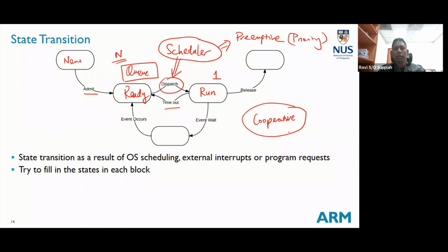It's a round robin kind of thing where you transition between every task, giving an equal share to the different tasks in the system. In an RTOS, you have to have a scheduler that is preemptive in nature and where priority is the base deciding factor on who gets to run. That's why I said earlier, priority is very important, because that determines which task is the most important in the whole system.